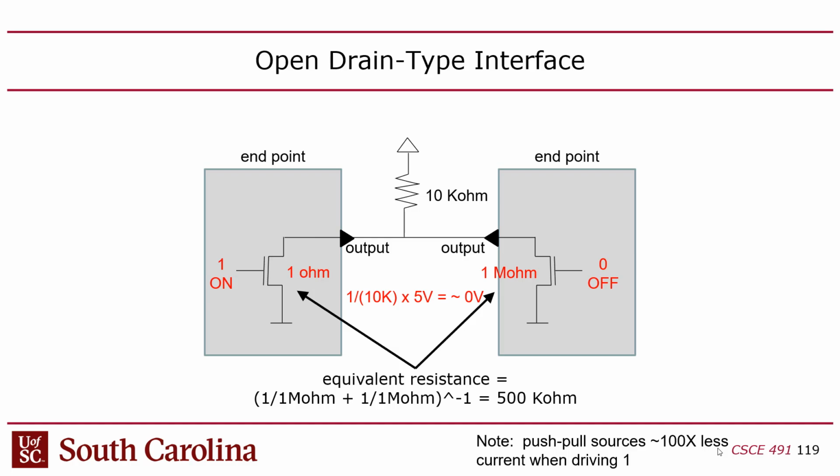But just to clarify, in the I2C protocol, which is what I'm about to talk about, the first thing you do when you want to take mastership is you pull down. So that's the signal that you're trying to take control, right? That's the first thing that happens. When the bus is idle, it's going to be at logic level 1, because no one's pulling it down, and so it's going to be at a voltage relatively close to VDD.